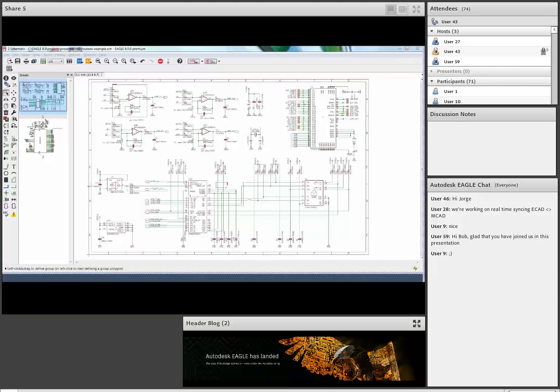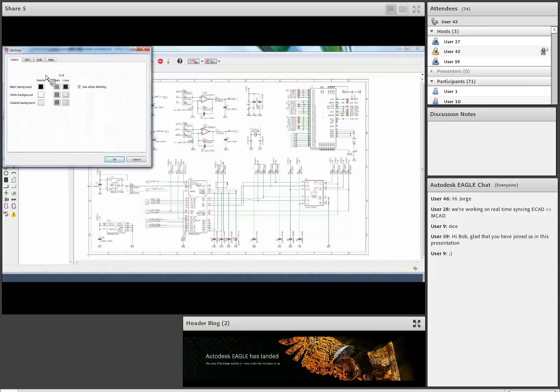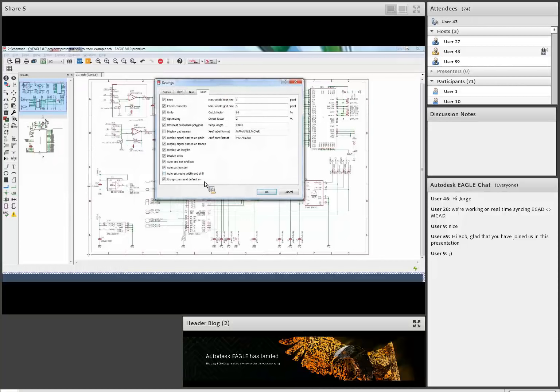Now, let's talk about our new feature, which is called the group command. This was an existing command that Eagle already had, but we've added some steroids to it. I'm going to do a couple of demonstrations. First, under your options set, if you go to the miscellaneous tab, you'll notice a group option available. By default, it will come up every time you start. Unless you deselect this option, every time you're idle during your Eagle session, the group command will automatically activate.